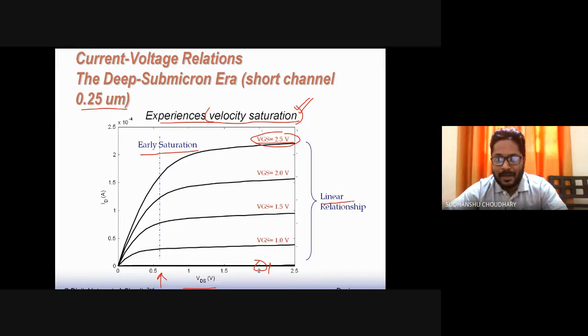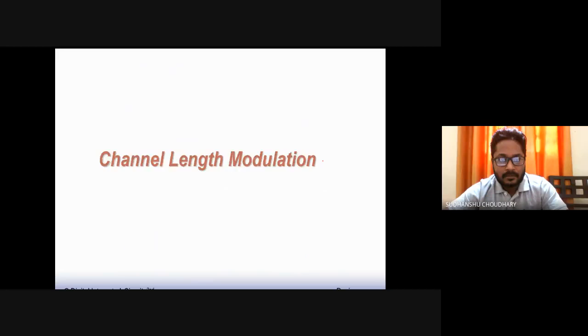Now this IV characteristic has a linear relationship with VGS, that is, I varies linearly with VGS. So this is important here. But in the long channel, the IV characteristic showed a quadratic relationship, that is, I was varying quadratically with the applied VGS. Channel length modulation we had seen already, that is, because of the reduction in channel length, the current was increasing. That can be modeled by bringing in this parameter lambda, which is the channel length modulation parameter.